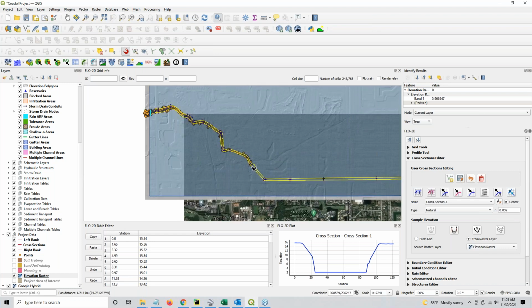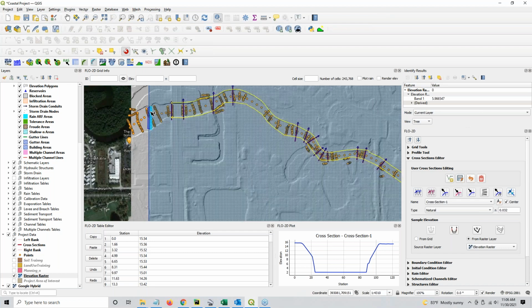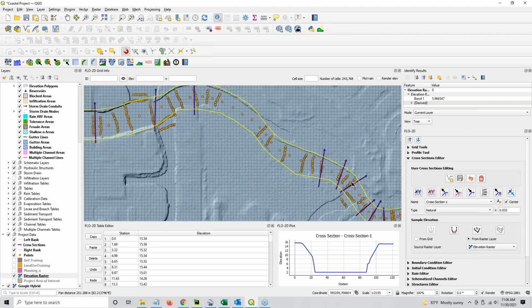And then the slope in this area would be determined by these points. And so I just tried to grab these bottom points along these little cross sections right here. I tried to grab a bottom point from these cross sections, apply that as my bed elevation, and gently push it upstream, even though we know with all those sandbars that the sloping down in this area isn't a perfect gentle slope.